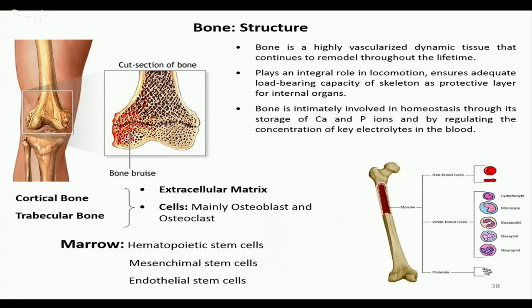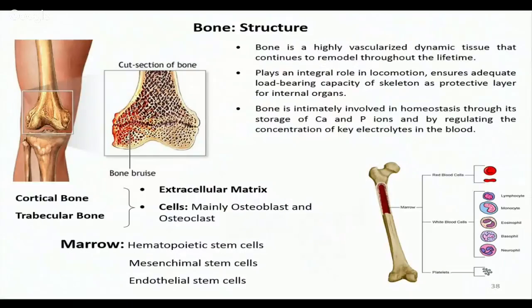So now you see that bone, I think already a lot of discussion was there. But I'll talk about bone again. So you see the cancellous bone, and we know the cortical bone. As you know, the cortical bone is all around. So any external shock that comes in will be transferred circumferentially, and then as it is transmitted to the cancellous bone, the cancellous bones are like struts, and they buckle and then again come back. This kind of buckling and coming back is actually a toughening mechanism for the bones.